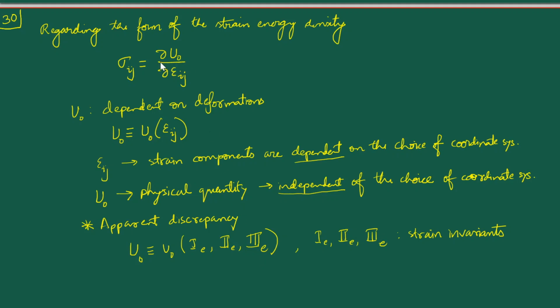If we take the first derivative of those cubic terms, you will end up with a relationship between the sigma and the epsilon which involves quadratic terms at best. You will never ever obtain linear terms. Remember that this is under the supposition that u naught has a linear dependence on I3, and if it were more than linear, then it's an even worse scenario.